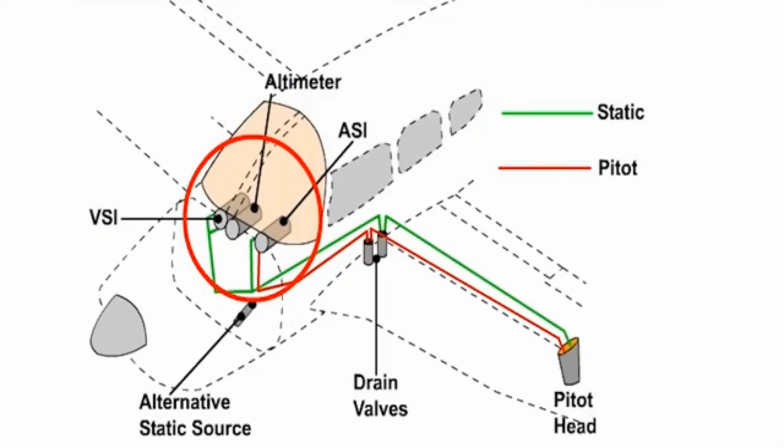The pitot-static system supplies both pitot and static pressure for the airspeed indicator, the altimeter, and the vertical speed indicator. Pitot and static pressure are usually sensed by a pitot head situated where it's not likely to be affected by turbulent airflow caused by projections from the aircraft skin.